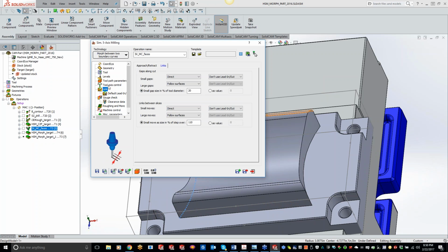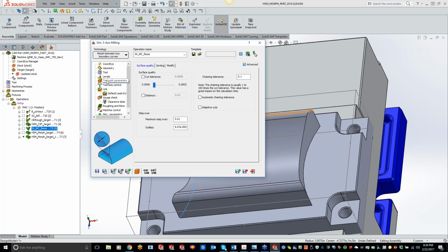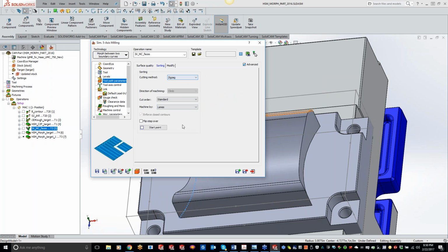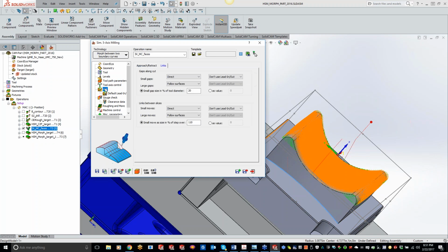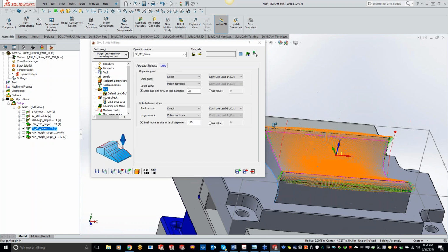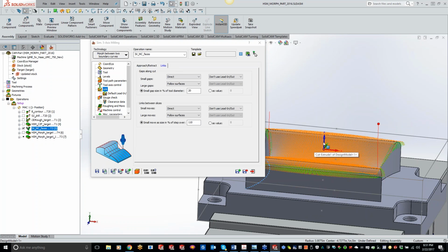And even if we go to our toolpath parameter sorting, and we are set to zigzag. Now you'll see, and I'm getting a little off topic here, but just by switching our links to follow the surface, we really eliminate a lot of those red movements in there.